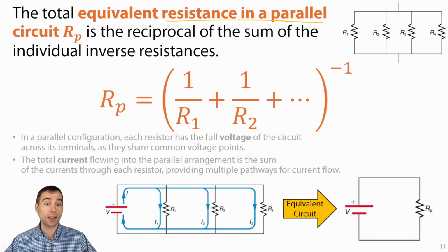And so if we think about electricity flowing into this parallel connection with 4 resistors, we can calculate the equivalent resistance of that circuit by redrawing it as an equivalent circuit, and we can calculate the equivalent resistance of a parallel connection of resistors using the inverse addition rule.